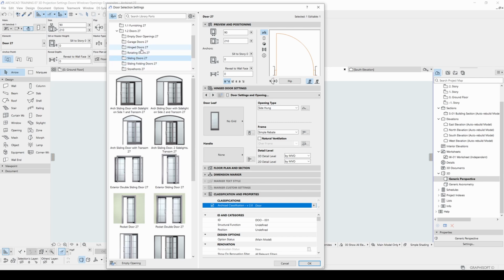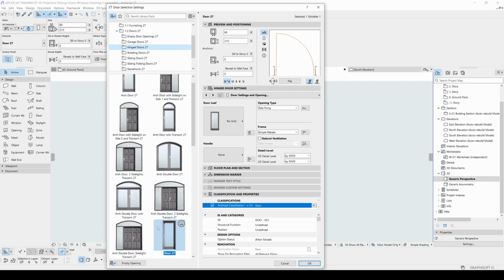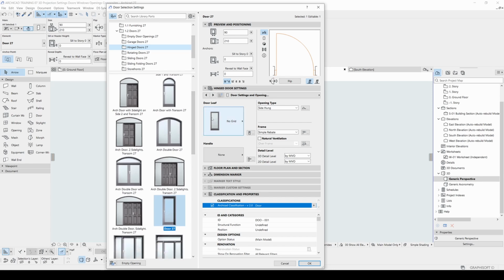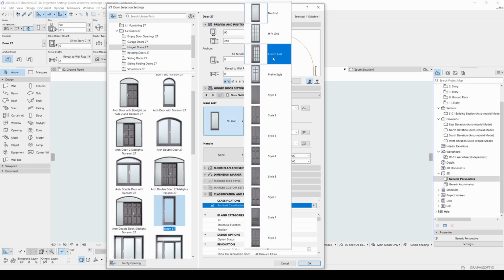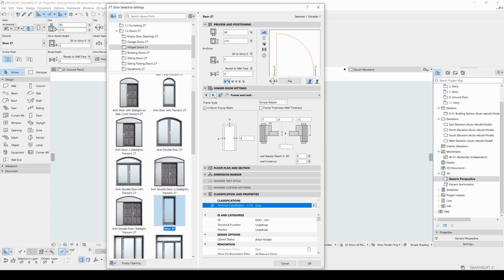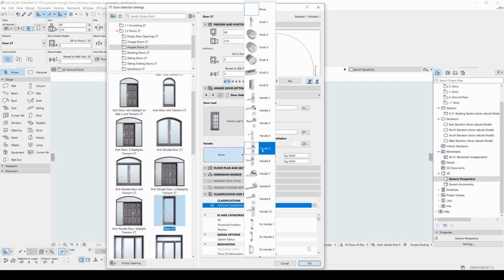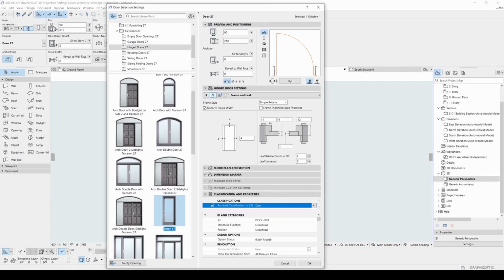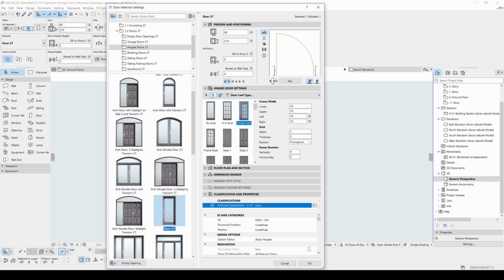For instance, I'm going to place hinge door. It's the default door, and after placing this, I want to change this door leaf to French leaf, and I want to add some handle, and after that I will make the left offset 5, 5 and 15, and I want to see a preview from here in the 3D or from the front, and this is our final model.